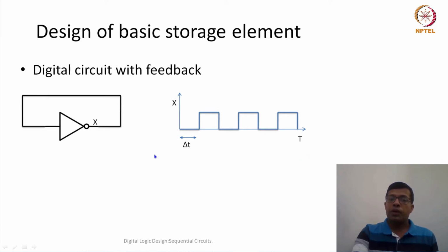So that could be a reason that this particular circuit is not usually used as an oscillator design, because first of all we cannot control the frequency, and also we cannot vary different frequencies, and this time period will also vary as the temperature or ambient characteristics change. But the question here we wanted to see was, can we design a basic memory element?